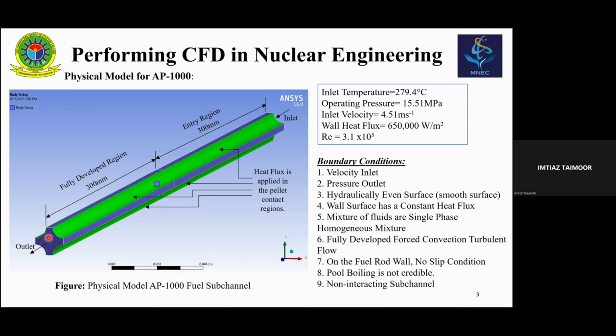Okay, I proceed, and I think whenever you go through the recording, you will have a better understanding. So this is the wall heat flux. That means in per meter square or unit meter square area, what is the heat flux that I'm giving? And then the Reynolds number, we can calculate it from the parameters that are actually available with us. We have to calculate the Reynolds number.